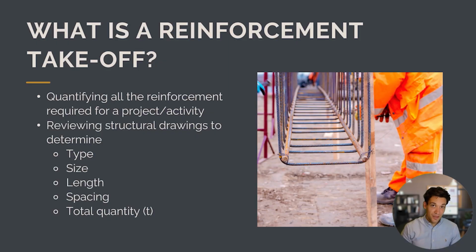So starting with the big simple question, what actually is a reinforcement takeoff? Well, it's the process of quantifying all of the reinforcement required for a project or a specific activity or slab. To do this, we'll review the structural engineering drawings to determine the type of reinforcement, the size of the bars, the length, the spacing, and then produce a total quantity in tons.